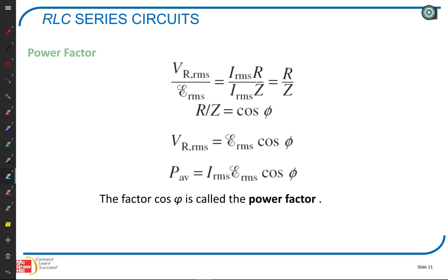That's all they really can do. They're delivering voltage at a certain level, and they measure how much current is going into your house, and that's what they charge you for. It's voltage times the current, multiplied by time, of course, because they're charging you for energy. But an inductor or capacitor returns the energy. Where does it return it to? The earth. Power company can't recover that. So it's not like they're going to cut you a break and only charge you for what you use. They charge you for what went out of their system into your house.